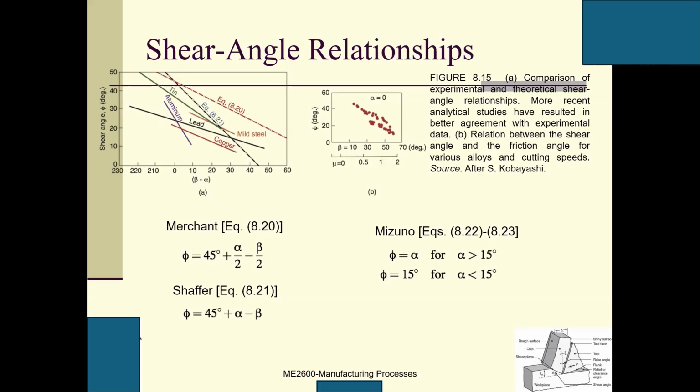The rectangle, right? What is the beta? Clearance, right? Relief angle, clearance angle. Okay, so alpha is a relief angle, and beta is a clearance angle or relief angle. These two angles are both for the tool.